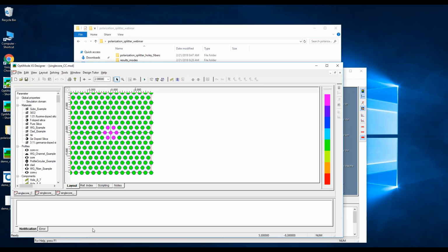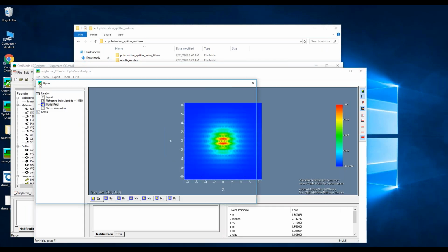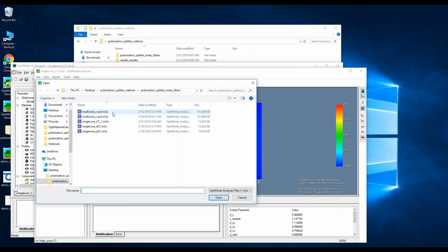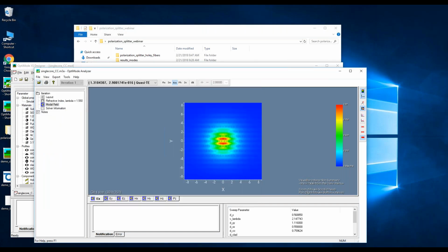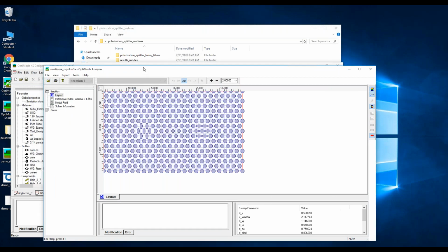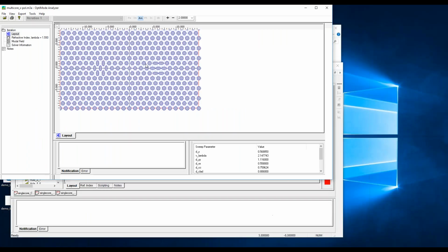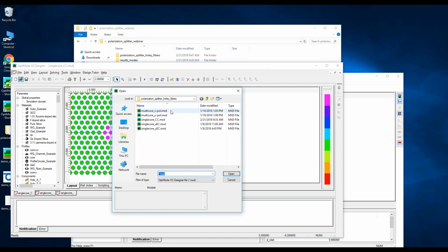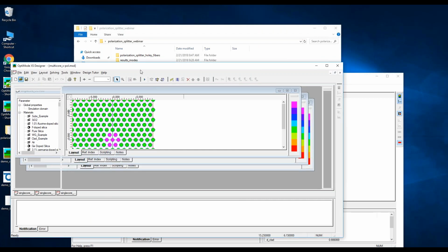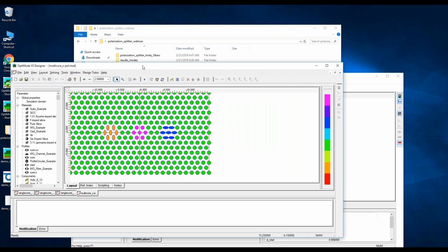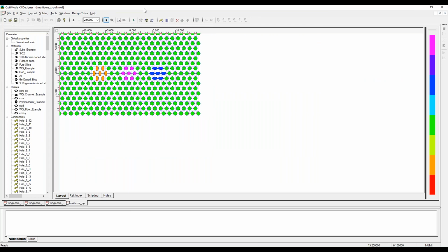And now let's look at one of the more interesting structures, which is the multi-core structure, which is this one. A lot more complicated. Maybe I'll open it up as well to really show the structure here. Right, so you take the 3 cores and you set them side by side. And then just like in the first slides, which showed the 2D mode solving, you get a symmetric and an asymmetric mode.